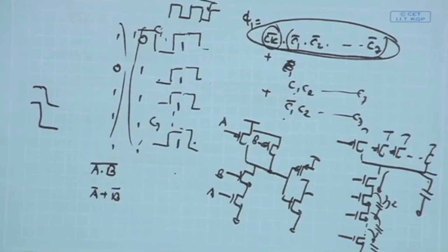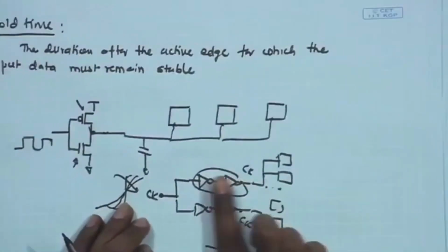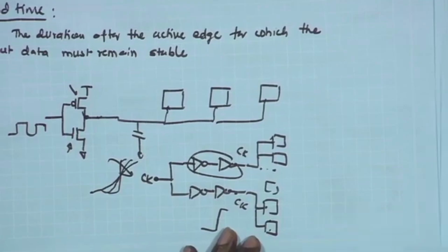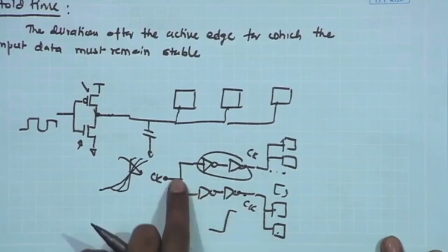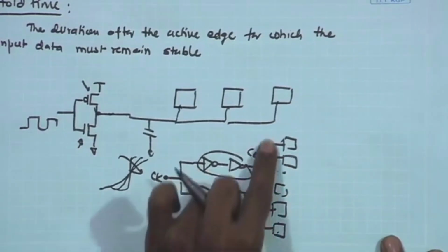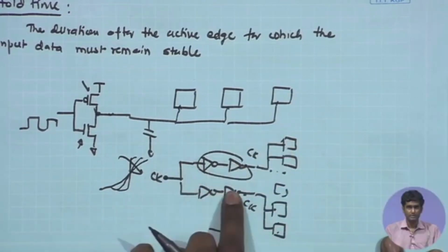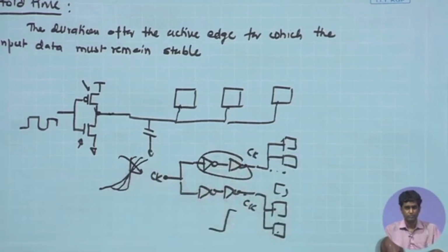So, in case of bifurcation, you added 2 inverter buffers. Why can't we simply divide it into 2 parts without adding the buffer? If you do not have this inverter, then the load capacitance remains the same. That is the main purpose, right? Dividing the load capacitance and making it smaller. So, if this was connected to 8 logic gates, then the fan out of this was 8. Now, I inserted some buffers, and this buffer is driving 4, this buffer is driving 4. So, the fan out of each of these is 4.